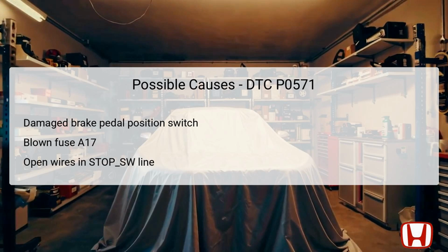Lastly, there could be open wires in the stop SW line, which could interrupt the communication between the brake pedal position switch and the ECU.